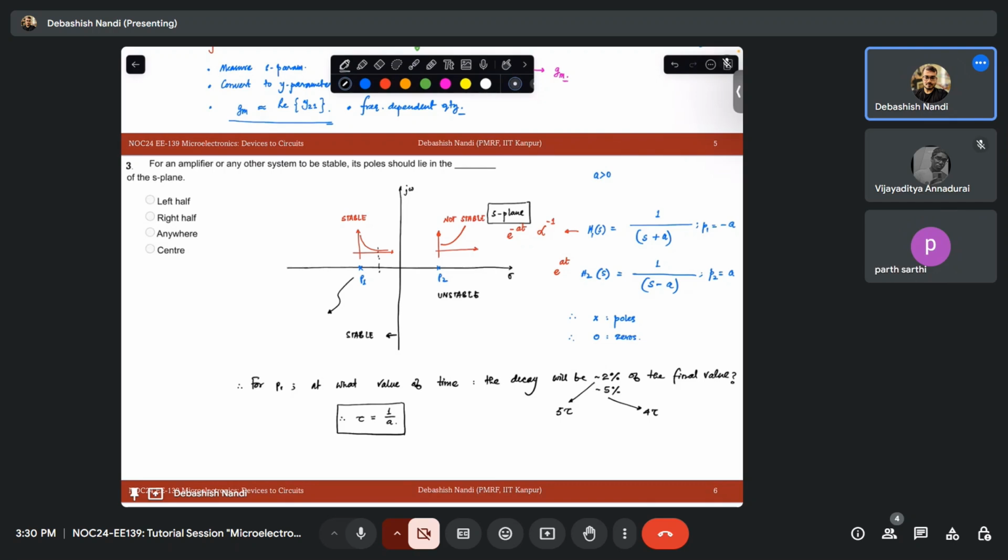By the way, is it necessary that for a system the number of poles and the number of zeros has to be the same? Where is the zero in this case? I don't know the physical relevance of this, but when we plot root locus, the loci originate from the poles and terminate at zeros, so they should be equal on paper.